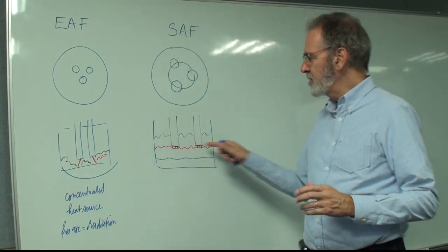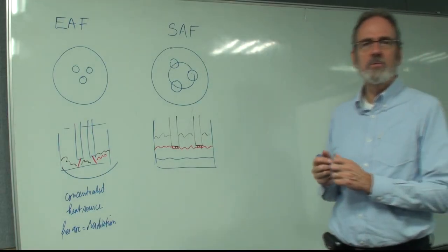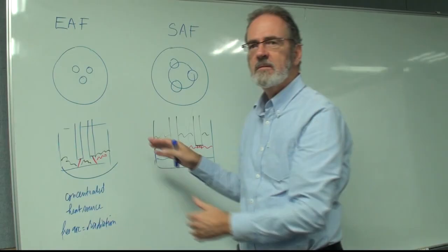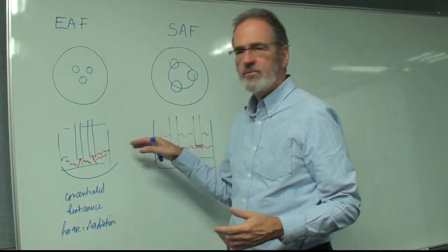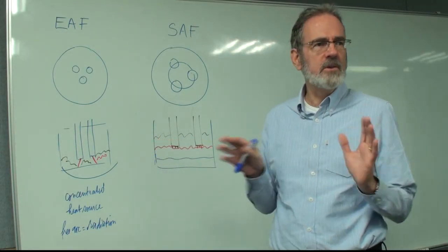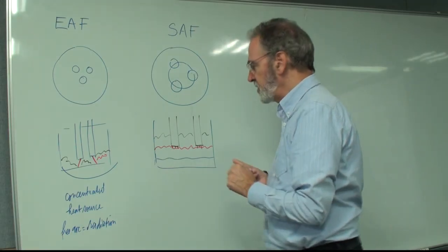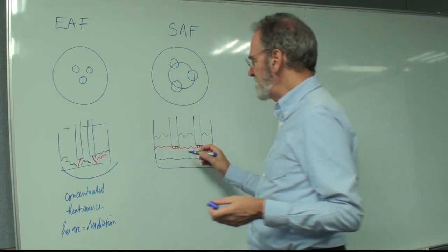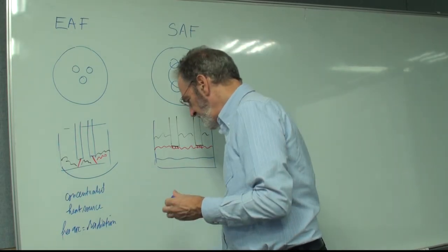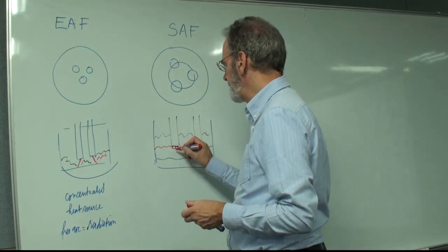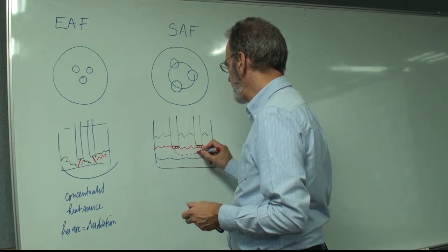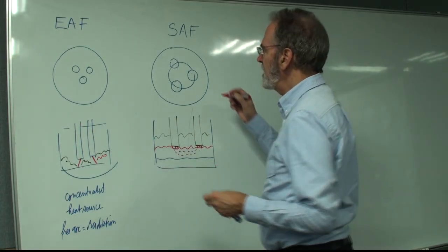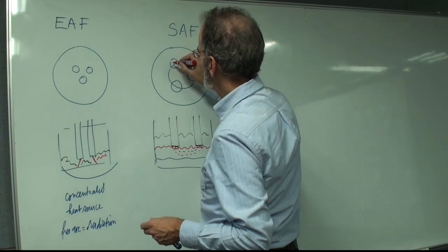The heat from the small arcs is all transmitted to the slag because there is no free space. The arcs will not radiate on the walls. There is no risk. But the second mode of transfer is resistance heating between the electrodes, and this one is organized like this.